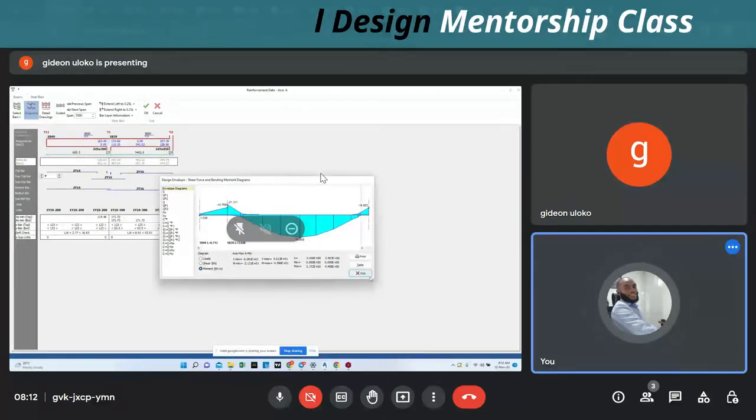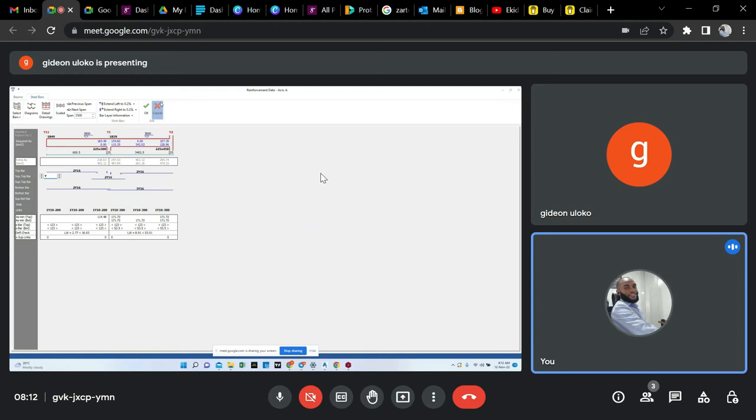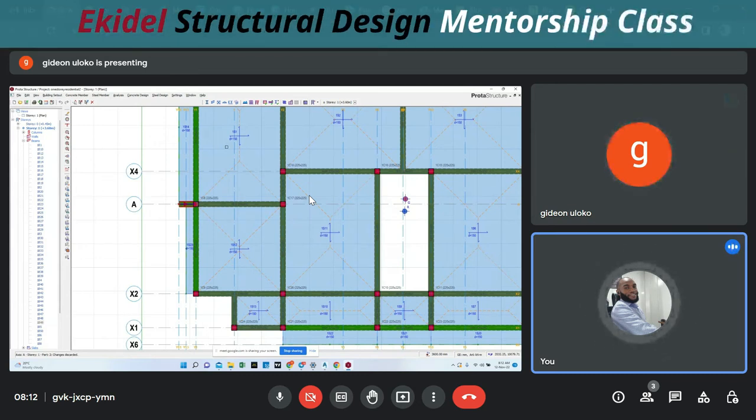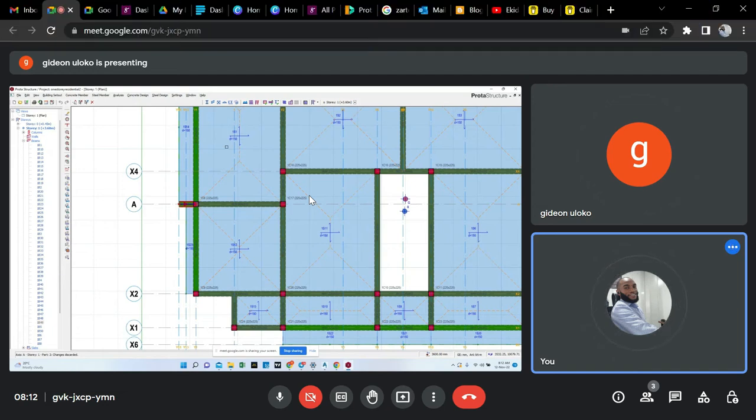But basically, normally every beam end that is not a cantilever is meant to be hinge. That means that place should be zero. Moment there should be zero. So with that now, we have to apply these things. And also, the reason why that is very important is because if you have a higher top moment where it's meant to carry zero reinforcement, and you're giving it a reinforcement, invariably the cost of your design will be very, very high. You understand?